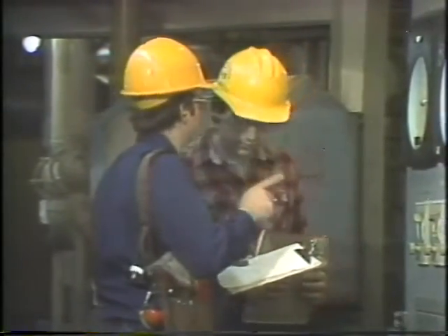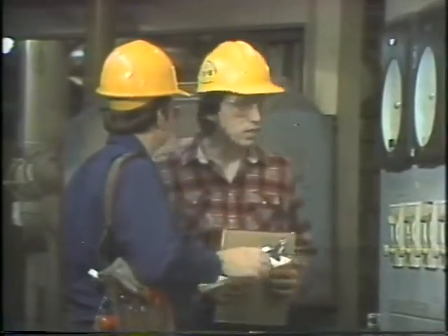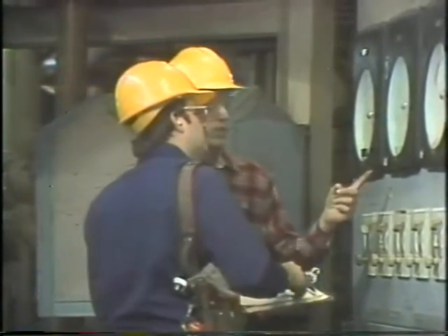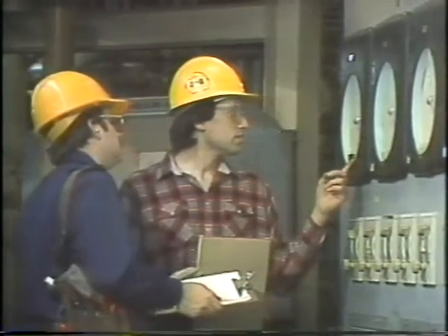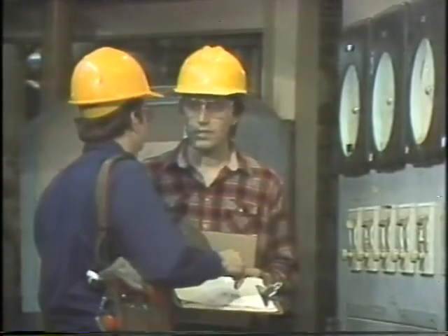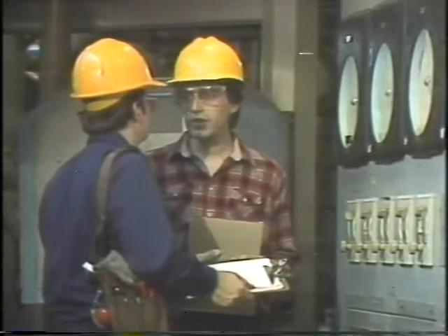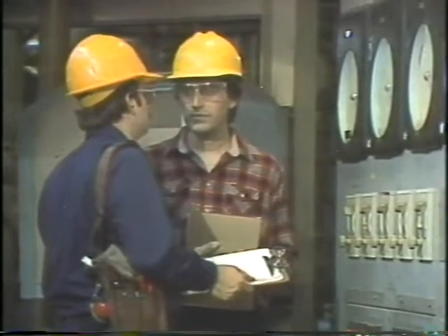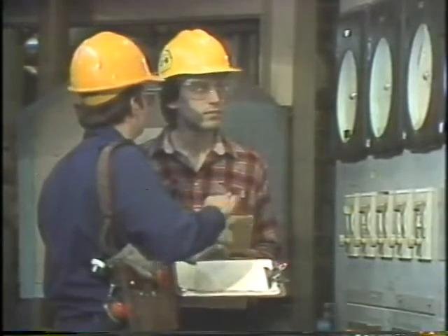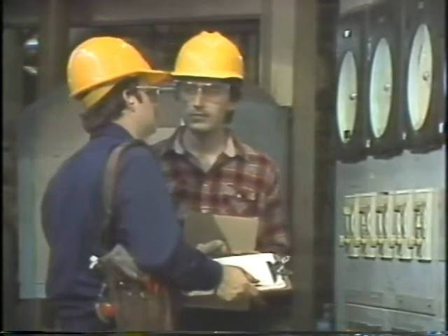When Bob talked to the operator, he found out that the system had been operating under normal conditions when the problem was first noticed. There hadn't been any unusual changes in plant demand for steam, and there hadn't been any equipment failures that would have upset the water level. The operator said the system was controlling in automatic all right. It was just that the drum level and the feed water indications were off. The steam flow indication was okay.